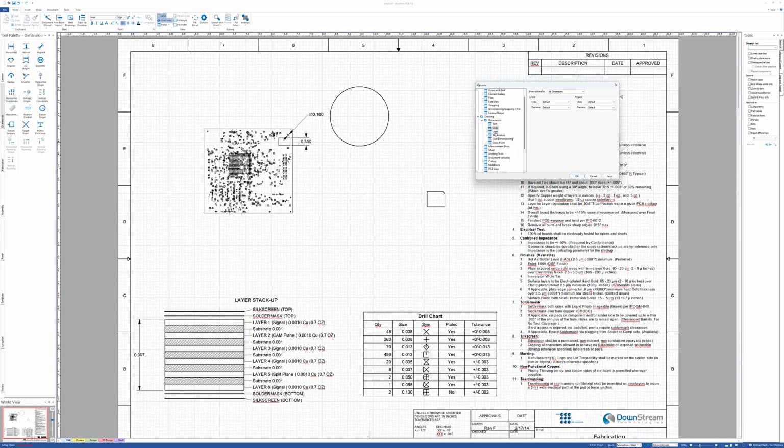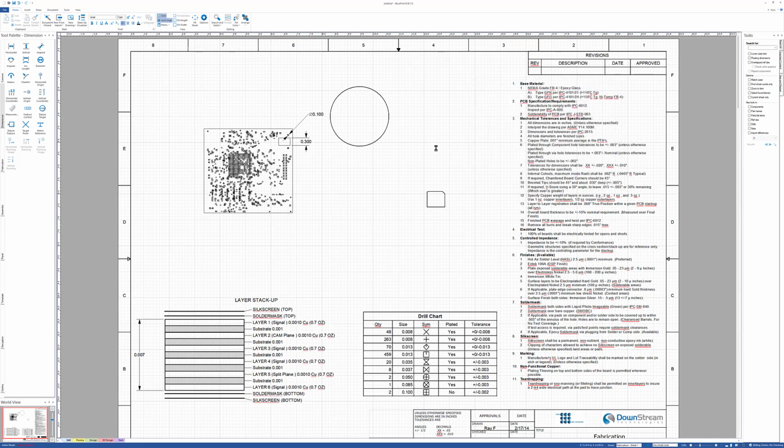What do the lines look like? When you place the lines, what's our highlight color for floating dimensions? And we'll see that in just a second. Terminators, what do they look like? Dual dimensioning is an option, as well as cross-point dimensioning. Okay. So all of those are available in our options dialog. That means that everybody will be doing everything the same way.